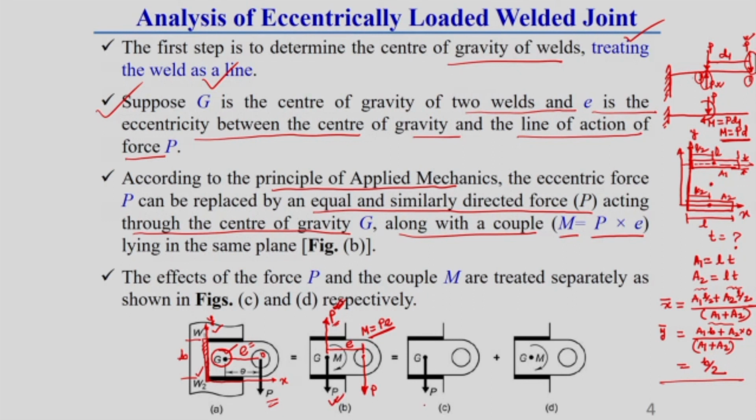After that, I divide this force-couple system into one force system and one couple system. Here you see, this force-couple system we can represent separately: one subjected to a force P and one subjected to a couple M. That means, by the principle of superposition, at the same location there is a force P and there is a couple M.